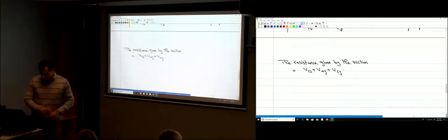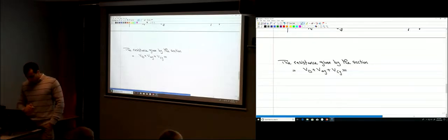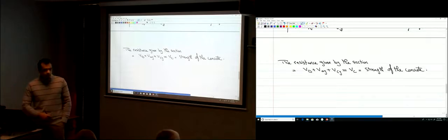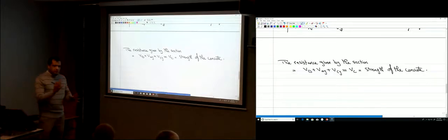okay? But the ACI code makes things easy for you and says the summation of those three terms, we're going to call them VC, the strength of the concrete. Okay? That's the summation of those three terms. That's the strength that the concrete can develop on that surface.